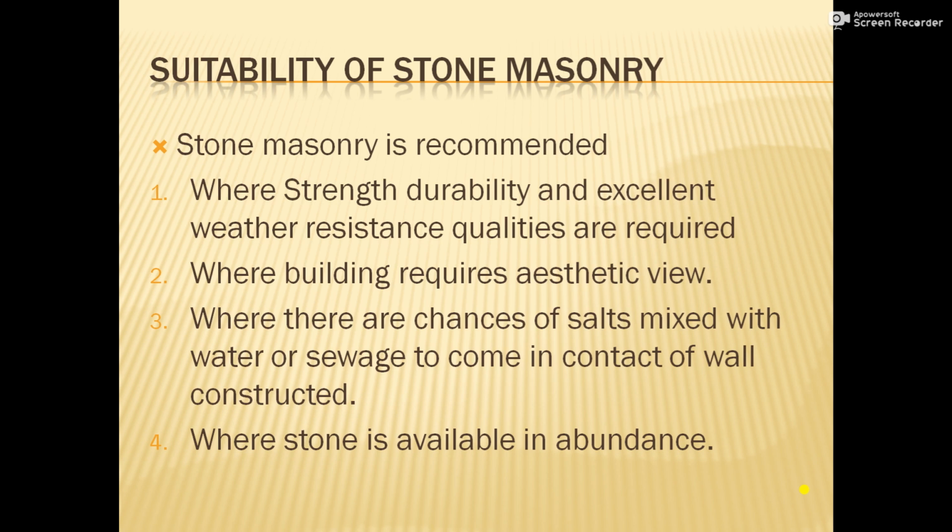Next, the suitability of stone masonry. Stone masonry is recommended where strength, durability and excellent weather resistance qualities are required. As stones are strong enough to carry large loads, the durability of the structure is more, and where excellent weather resistance is required, we recommend stone masonry.